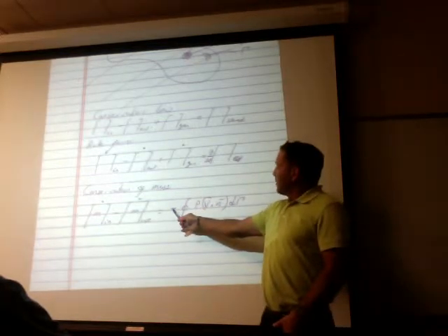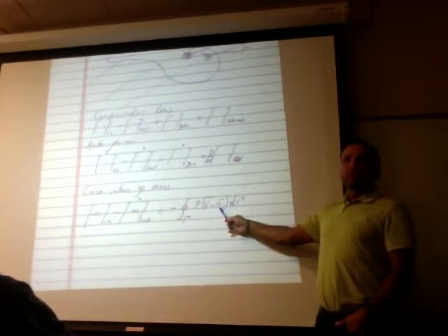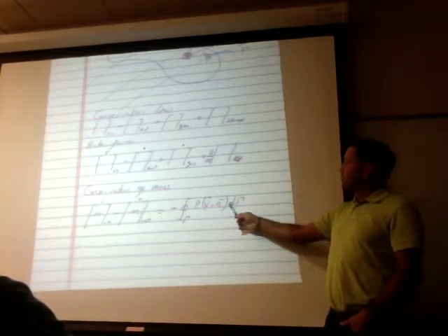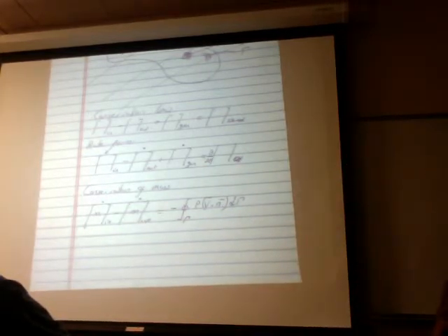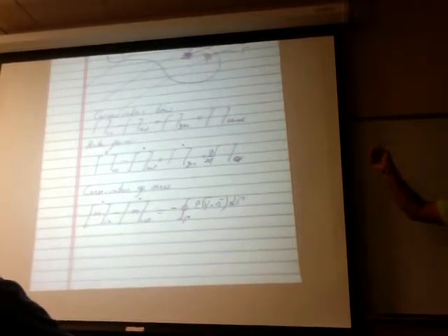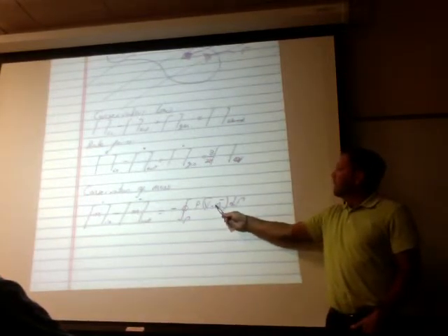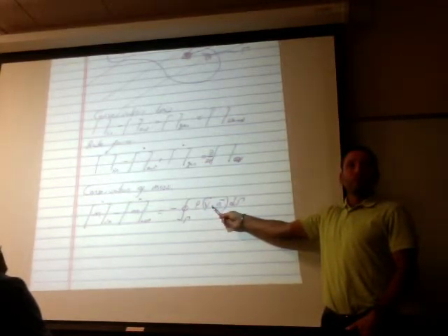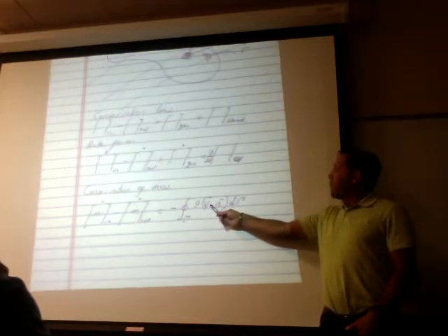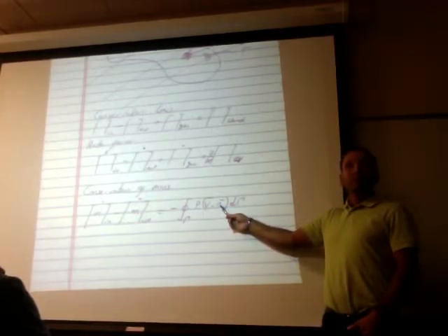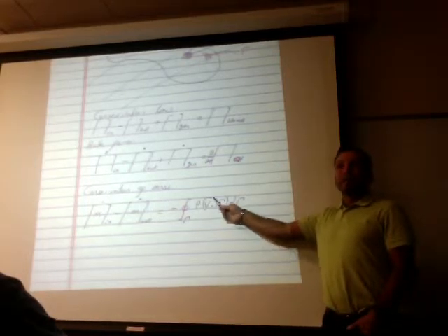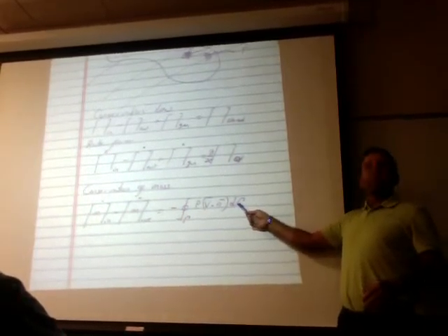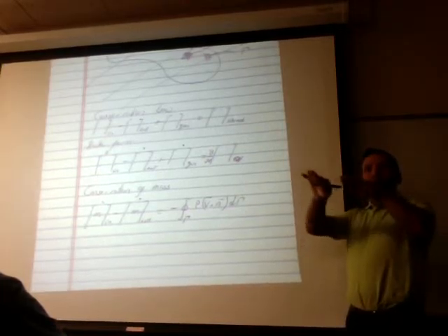First of all, we define this as in minus out, but it's negative because the normal vector always points out. The way we define the normal vector, according to our sign convention, the normal vector always has to point out of the control volume. So if you multiply the velocity field times the normal vector and you get a positive number, it's because that velocity is leaving the control volume, right? If you multiply the velocity times the normal vector and you get 0, it's because it's not entering or leaving in that particular differential of gamma, because they're parallel to each other.